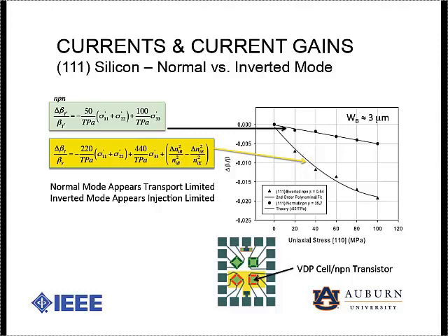If we turn the transistor upside down and operate it in inverted mode, then we expect to have a huge back injection current, and that ought to correspond to this equation, and it does. The initial slope here is easily modeled by the piezoresistive equivalent coefficient, and then we're getting curvature that we can predict from those Ni squared curves. So one of those is transport limited, and one of those is back injection limited. We haven't had time yet to check those by measuring the temperature coefficient.